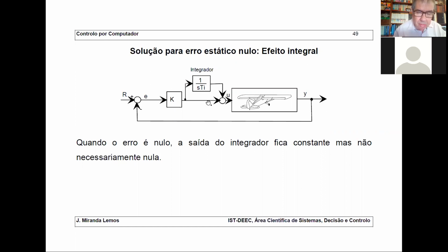Now, we should also remember stability. When you are adding poles in the feedback loop, you should be careful because when you do the feedback, the poles change their positions and they go to infinity or to zeros when you increase the gain. The ones that go to infinity can go to the right-hand plane.